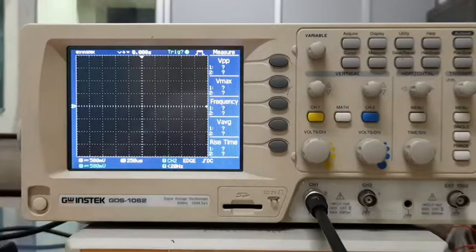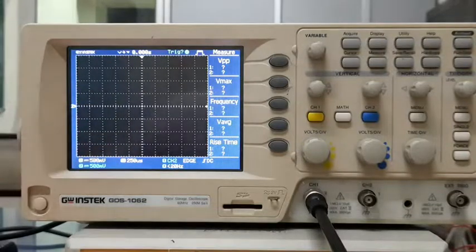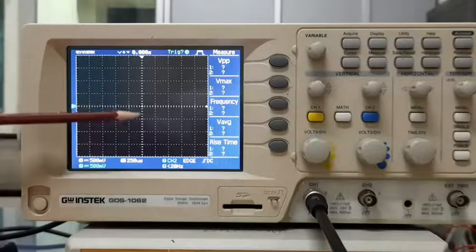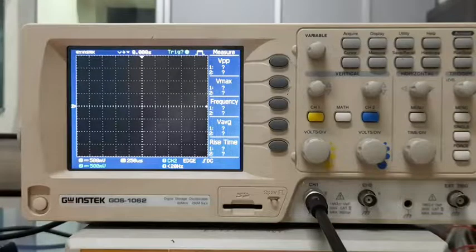So first we have to set the range properly to see that signal. By range, I mean, let's say, the vertical scale. The vertical scale shows you the amplitude, or the voltage value, of the signal at different times, because it's a time varying signal. The vertical scale is graduated, so you can see these different boxes, and the boxes are also graduated with dots.